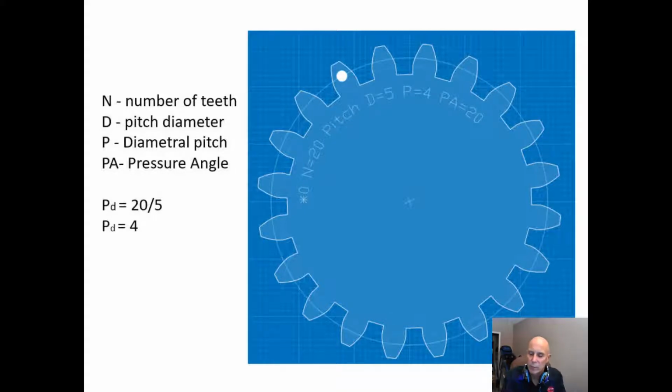And what I've done is I've printed out 2 different ones. This has a pressure angle of 14.5 degrees. Now, these teeth both run nice and smooth. This has a pressure angle of 20 degrees. And again, these run nice and smooth. But if you mix up a pressure angle of 14.5 and 20, they don't run smooth. And what you're going to get is some unusual noises and extreme wear out of that gear. And it probably wouldn't be long before it's failed.